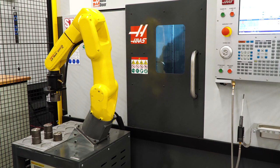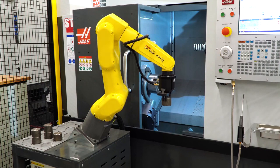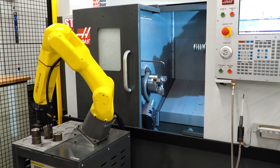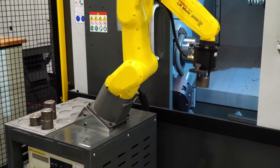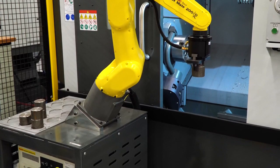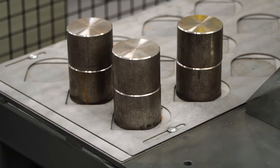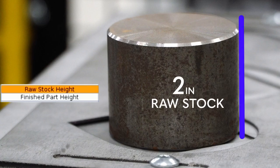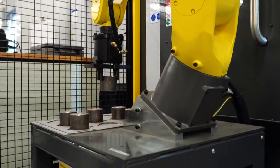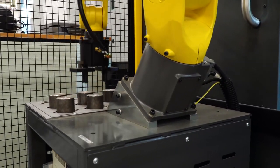The robot will start by picking up the stacked stock in pocket 2, then stacking the finished parts in pocket 1. When pocket 2 is empty, the robot will then pick up the stock from pocket 3 and place the finished parts in pocket 2, and so on. You will need to enter the height of both your raw stock and your finished parts so that the robot knows where to pick up and place your stacked parts.